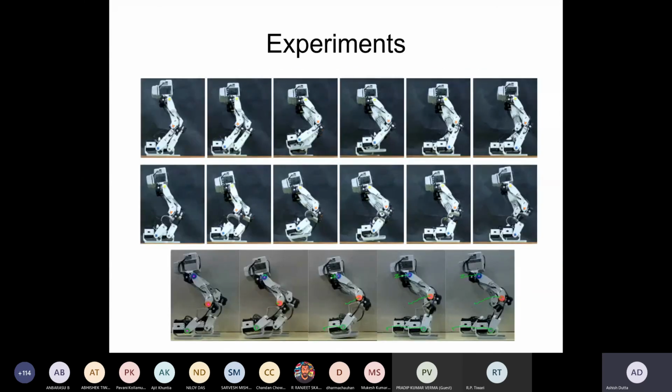We track the trajectories, and what it is showing is that the trajectories are not uniform or not very smooth, but they have all kinds of jerky motion. That was expected. There are advantages and disadvantages. Series elastic actuator in the world is today still a research problem. A lot of people are working on it because the requirement is in robot-human interaction.